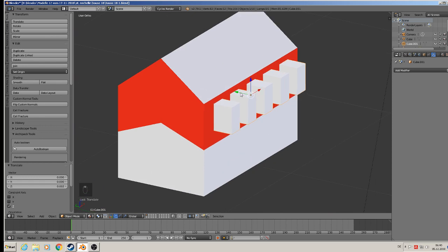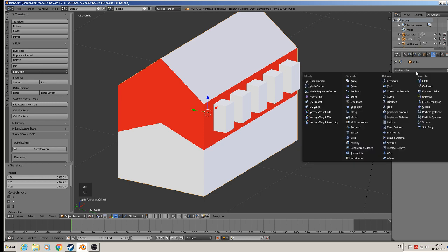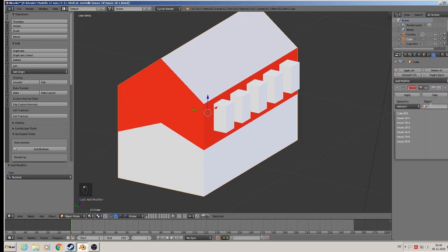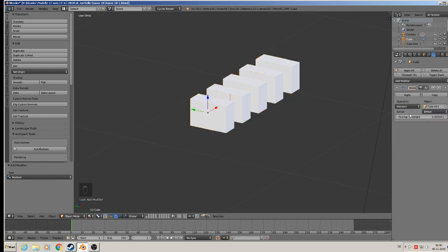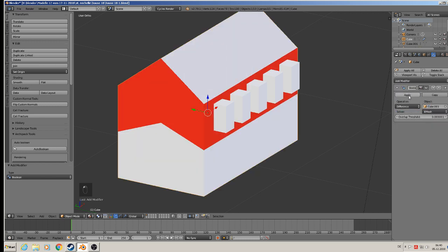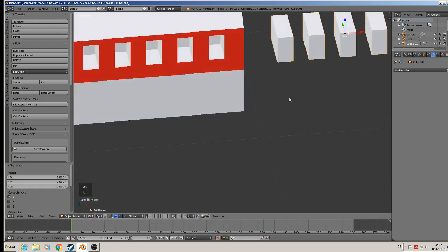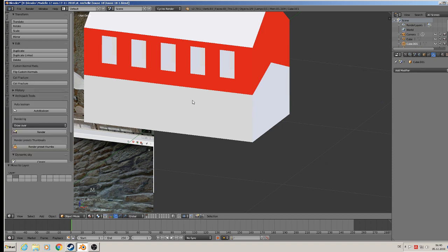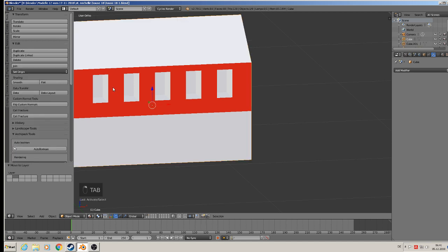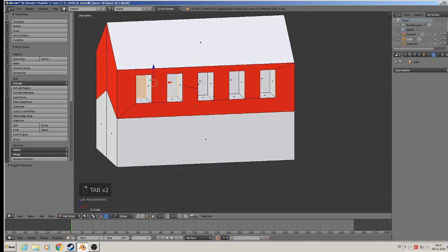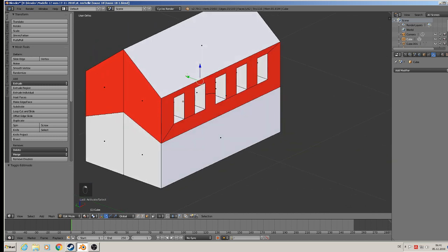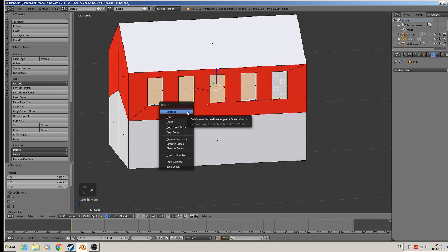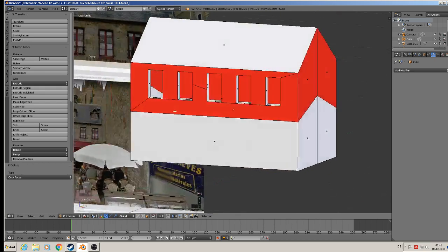Yep, it's good. So the name of this cube is Cube 1. So we go to the house, right click, then boolean, and take here the Cube 1 and say it should be the operation difference and apply that. So we have the holes in. We move that to the second layer, M to move, and then second layer. We see the windows are too deep, so we get the back faces and bring them nearer, and X, only faces. So this opens up now. Good.